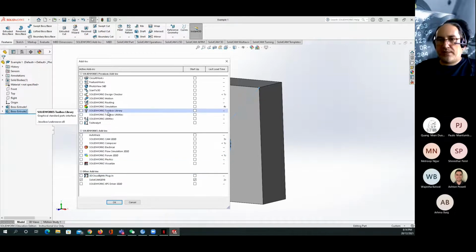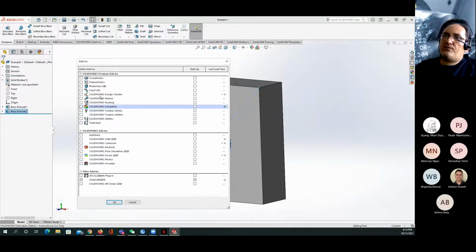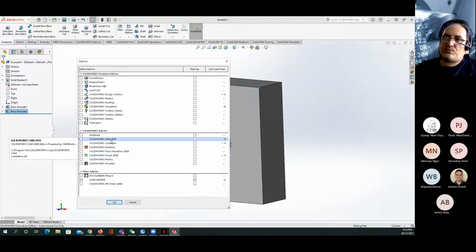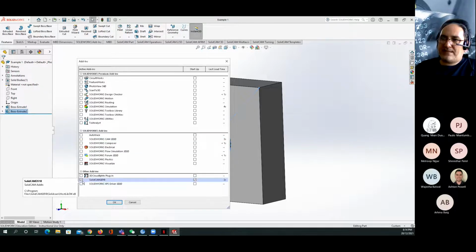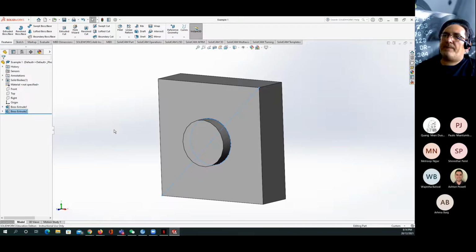To make the Solidworks run lighter, you remove all the add-ins that you don't need, including the Solidworks CAM, which does the same work, but I prefer SolidCAM, which is more advanced and very popular in the industry. So just take both. This will make it start at startup, and this one will start just to add it within the work, and you will see these tabs available for you. Say OK. Now I will start the operation of SolidCAM.